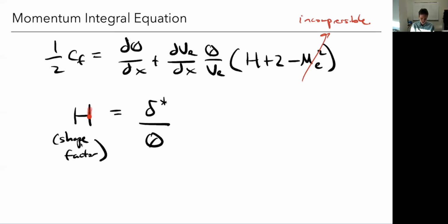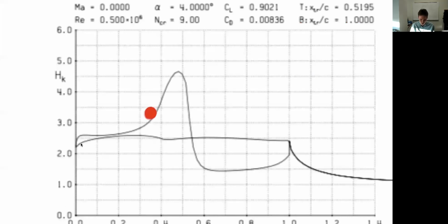And we're looking at two surfaces. This is over the upper surface and then over the lower surface. So over the lower surface, not too much is happening. Over the upper surface, this is increasing rapidly and then it drops. So you might ask yourself, well, what's happening here? Well, right here is where we transition from the laminar flow to the turbulent flow.